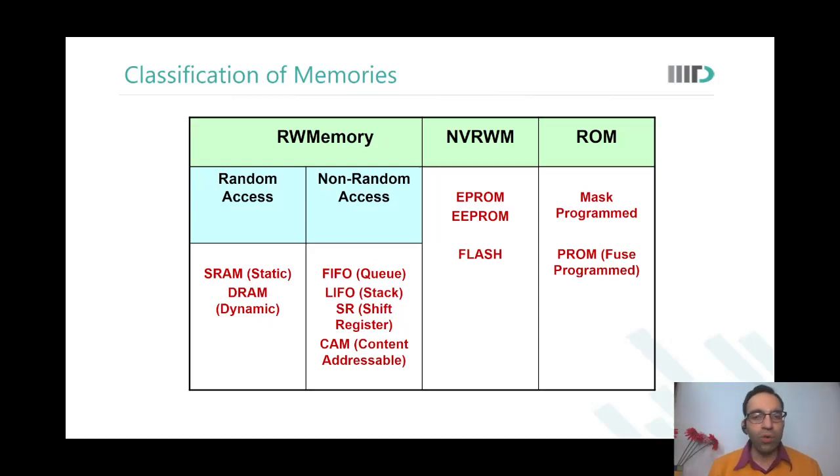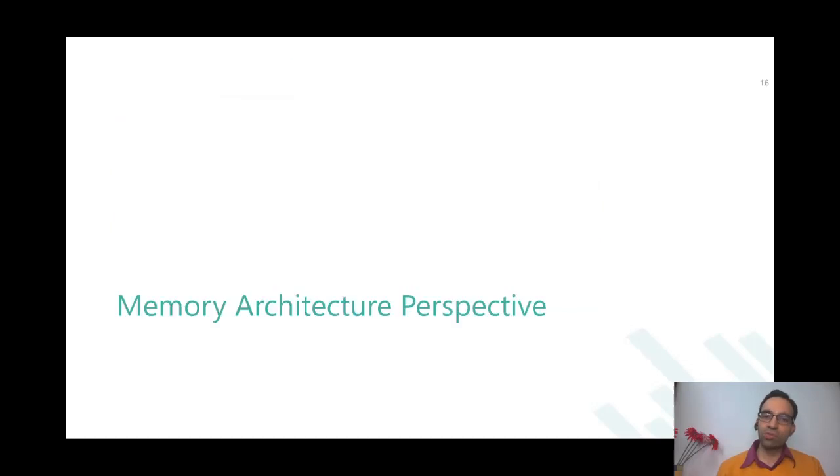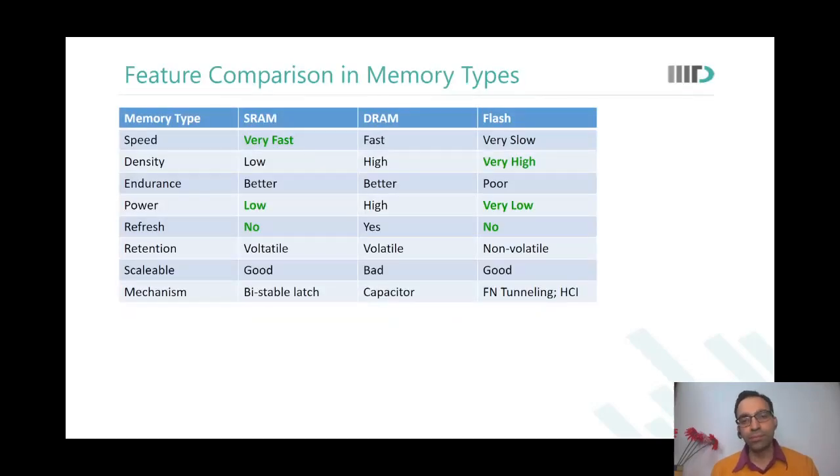Great. So now whatever be all these kinds of memories, whether it is PROM or ROM or FIFO or SRAM or DRAM or flash, whatever it is, there is a structure to it. Yes, please. Can I say that the PROM is storing the information of which cell is working properly and how many extra cells are available to us, so that it can allocate in the future? PROM will not do those evaluations itself. PROM will only store the location of the failing cell, for example.